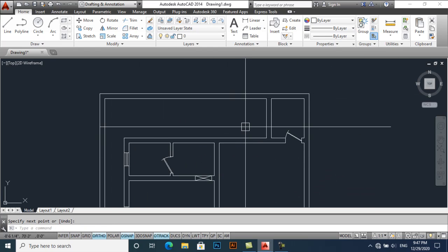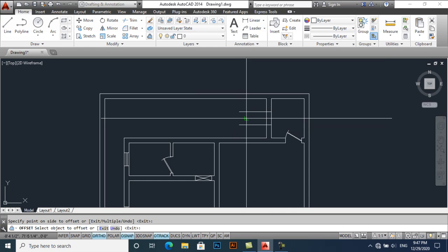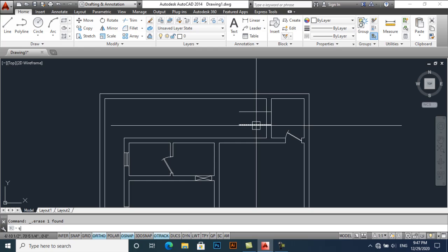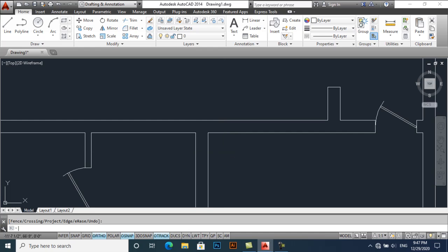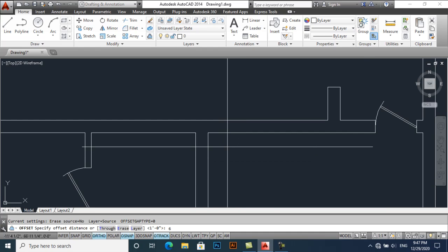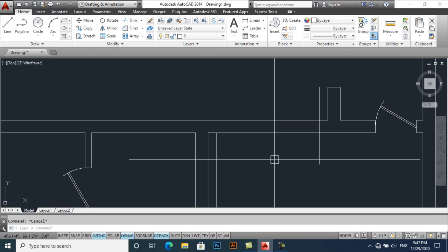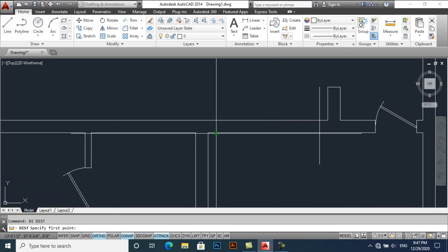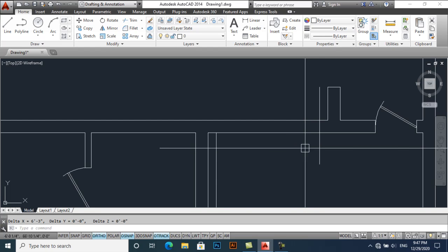With this process, with the help of multi-line, you can speed up your design. Offset 1 feet to each side, delete this one, trim. Now offset 6 inches, and offset 6 inches. Let's inquire our distance first. I think this will be 6 feet 3 inches.